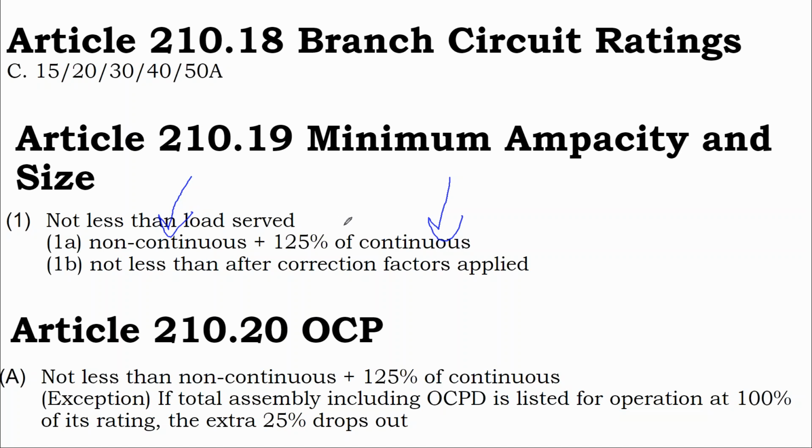And so we're saying, hey, continuous loads have higher operating temperatures, and so right off the bat they need a 25% oversize in terms of amperage. And that is just a common rule, if you're shooting from the hip and not flipping through your code book and identifying what the oversizing is, the general case is you take the amperage and you oversize by 25%.